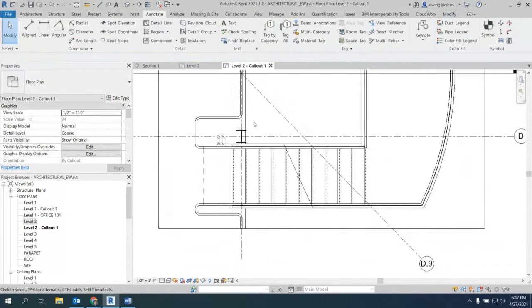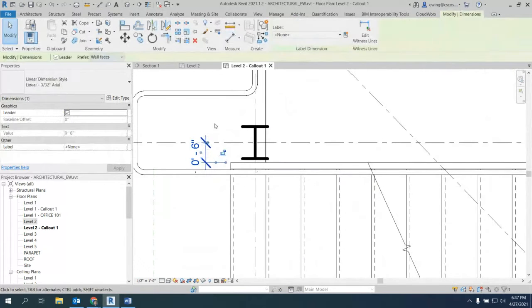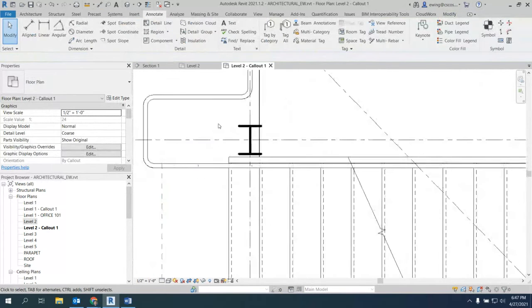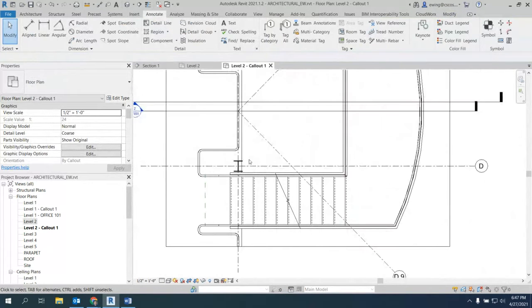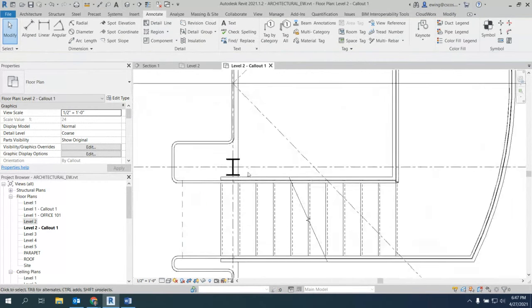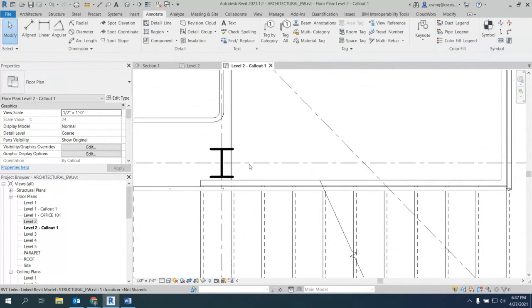Can you repeat that one, please? You betcha. So what I did was, because you remember, I was like, I think we need to offset this up to column line minus 6 inches. We need to tell them that was the decision we made to lay this out. So we're just going to add a simple dimension from here to here. On the annotate tab, we'll click aligned.